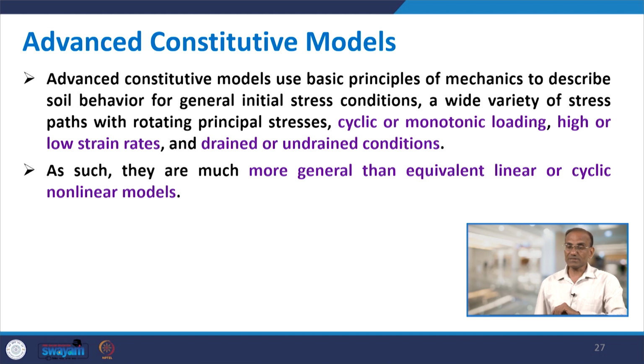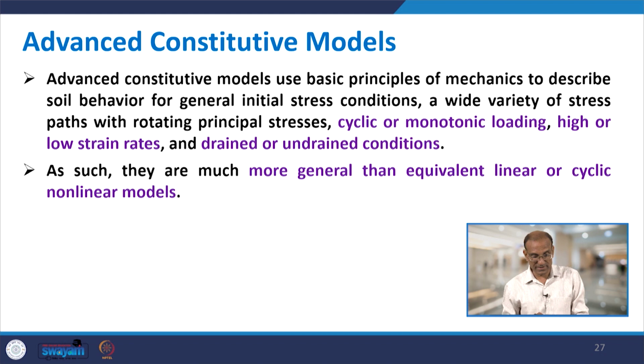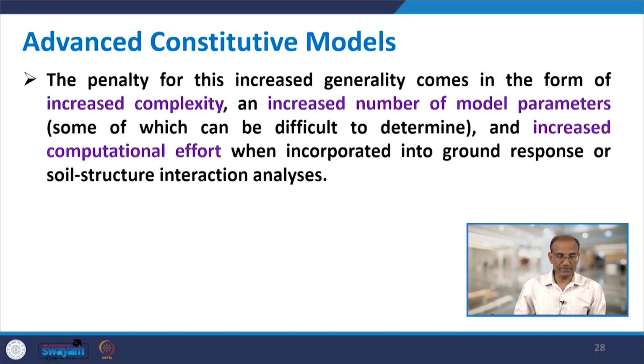Advanced constitutive models use basic principles of mechanics to describe soil behavior for general initial stress condition and a wide variety of stress paths with rotating principal stresses, cyclic or monotonic loading, high or low strain and drained or undrained condition. Therefore, these models are more general than equivalent linear or cyclic nonlinear models. So, they are able to capture many of the behaviors of the soil which were not considered in the equivalent linear model or cyclic nonlinear model.